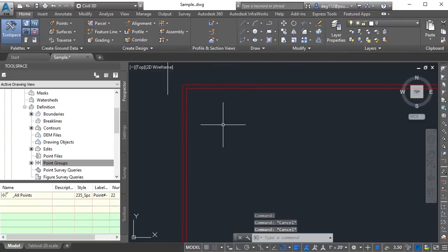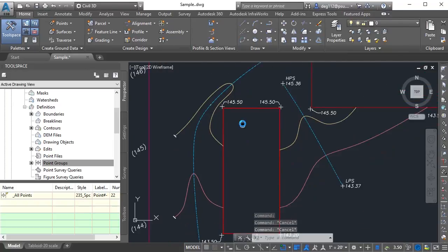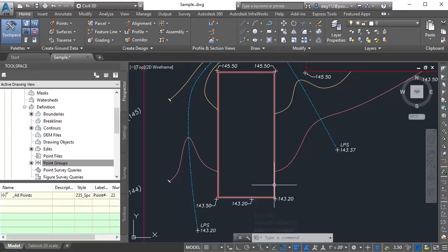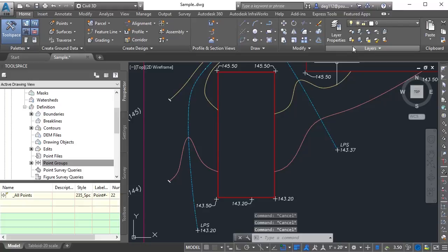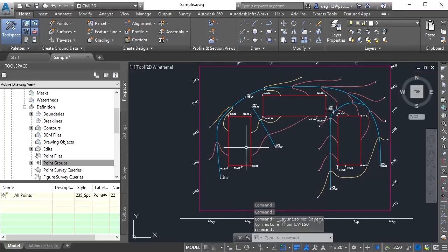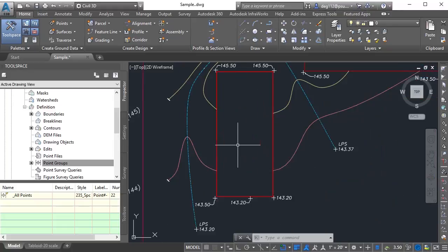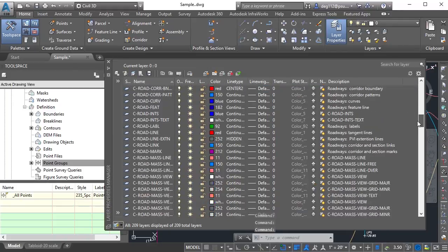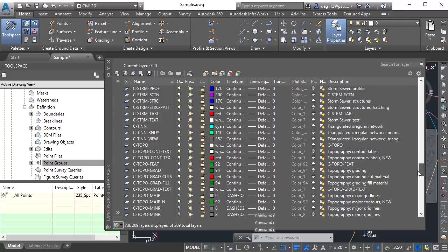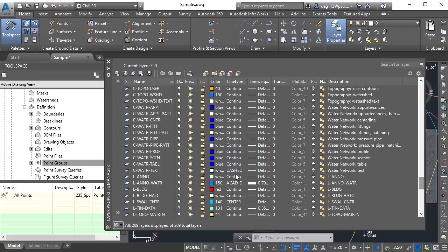Okay, so we'll go ahead and set this to an elevation. I'm going to choose the inside line and the FFE on this, and I don't remember what that was. I'm going to unisolate, put that back. I don't remember what the FFE is, so I'm going to turn on my layers here and just choose my L layer, which is where my FFE was written.